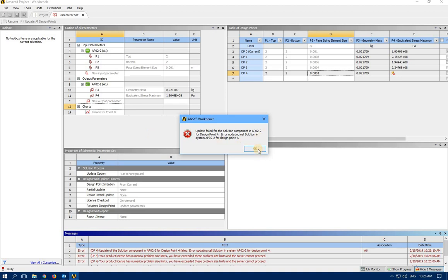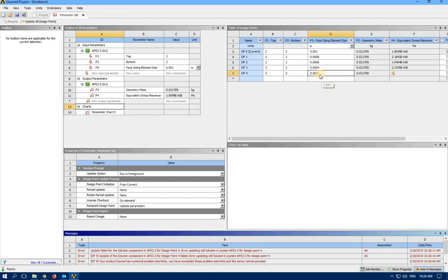Okay, it says there's a problem with the mesh. Let's go for 2. Sometimes when you select different mesh sizes, ANSYS can't fit all the mesh with the size you selected in the surface, so it gives you some errors. And the way I selected to refine the mesh wasn't proper way. You need to locally refine mesh at the stress concentration area.